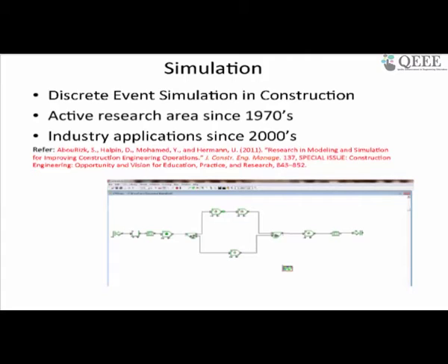It allows me to specify a distribution, not just a PERT distribution, but any distribution for the activity, and I actually simulate the project taking place. Kind of like 4D, but this is done purely in the mathematical space and not in the CAD space, and I can then get my distribution for duration. So a different kind of PERT, but in a discrete event simulation mode.